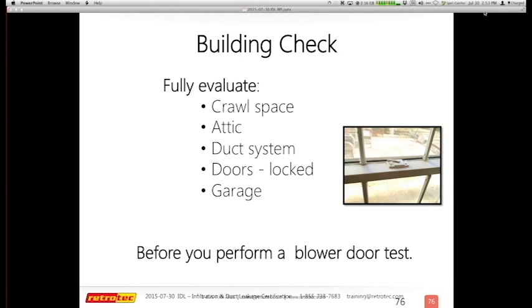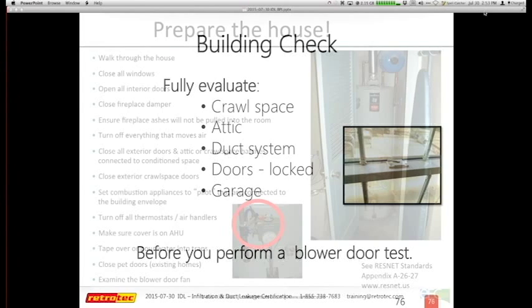Sometimes we actually do existing homes and we show up and we didn't really go thoroughly into the crawl space or attic, evaluate the duct system, or check that the doors and windows are locked. All those kinds of things make a huge difference. So even if it is a brand new home, you want to make sure that there wasn't a water leak in the crawl space, or the attic doesn't have some kind of issue or missing shingles that would have affected what you might be doing to the house itself.